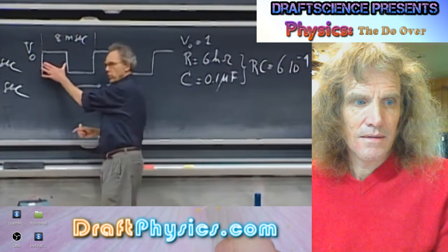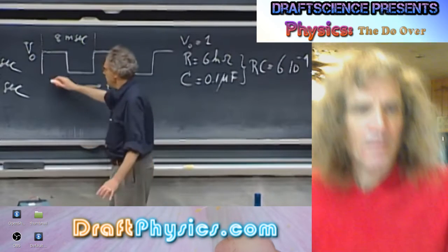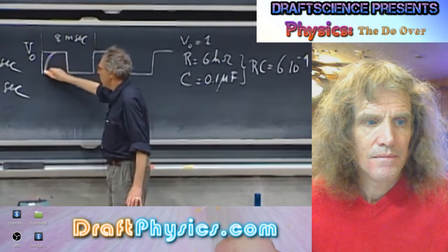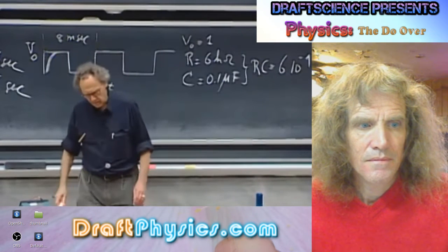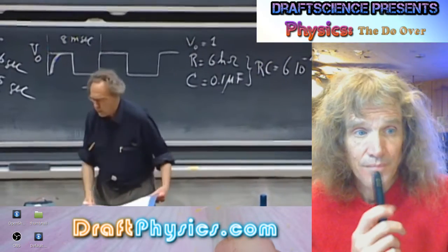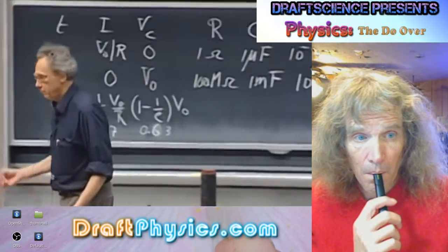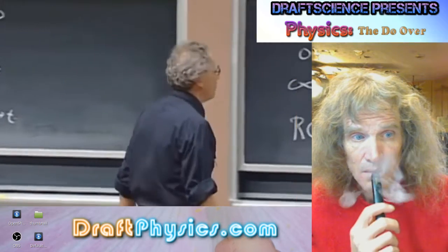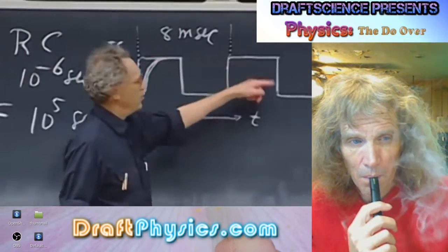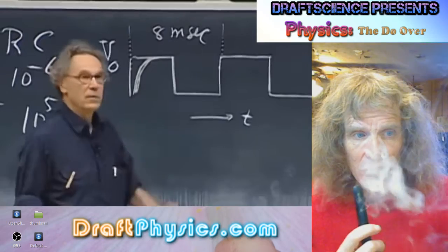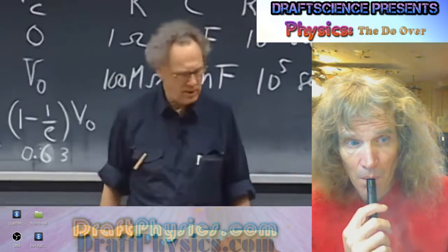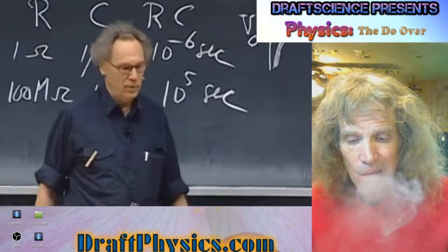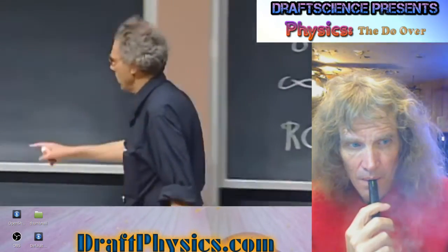Which is substantially smaller than 4. And so you can expect that the capacitor becomes almost fully charged in this 4 milliseconds. That's why I chose the RC time substantially smaller than 4 milliseconds. And my setup is such that I can show you the driving voltage of the battery. I can show you then how the capacitor is charged and how the capacitor is discharged with the time constant RC, and also how the current goes through the system. So I can show you also this curve.